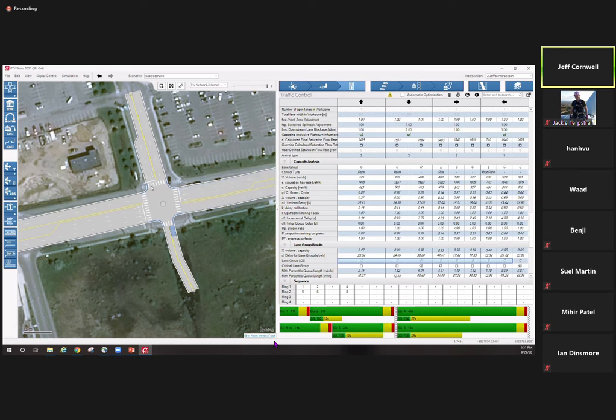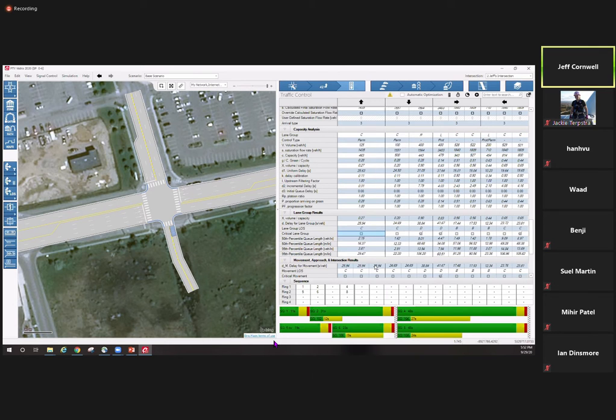And it would really help if you added a right turn lane and then a right turn overlap. If you can do those options and then optimize your splits, you'll get good levels of service that would be appropriate. So that's all I wanted to show today in this example, just how you can play with things to make things operate better.